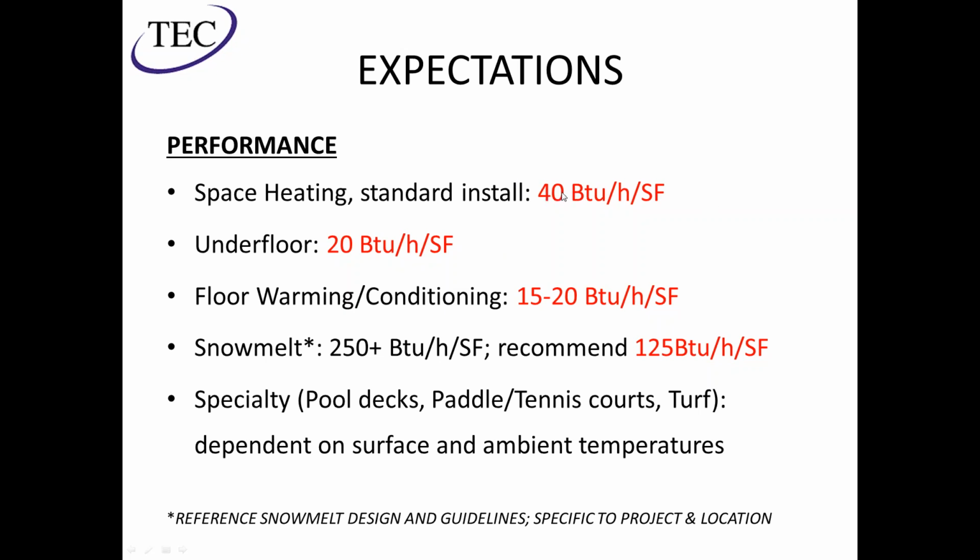Depending on the temperatures that the room requires, this may be able to go up to 50, but then you have to worry about the surface temperatures of the slab. If you're just doing floor warming or floor conditioning, it's not handling the main load, you're probably going to be looking at 15 to 20 BTUs per square foot.